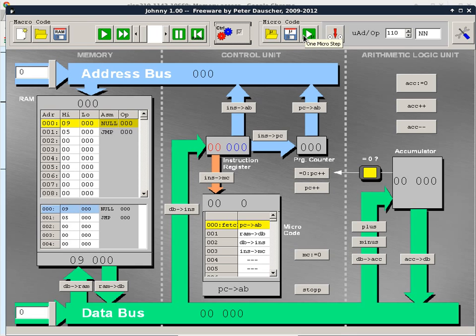Okay? Now, before we even single step through it, we can actually predict what is going to happen next. How can we tell what is going to happen next in terms of microcode? It's all down here, isn't it? So the highlighted portion is basically what we are doing. These 4 microcode steps collectively are called the fetch cycle of a processor. These 4 microcode steps are responsible for reading the next instruction that we are supposed to execute. Okay, so let's take a look at these 4, and then we'll trace it.